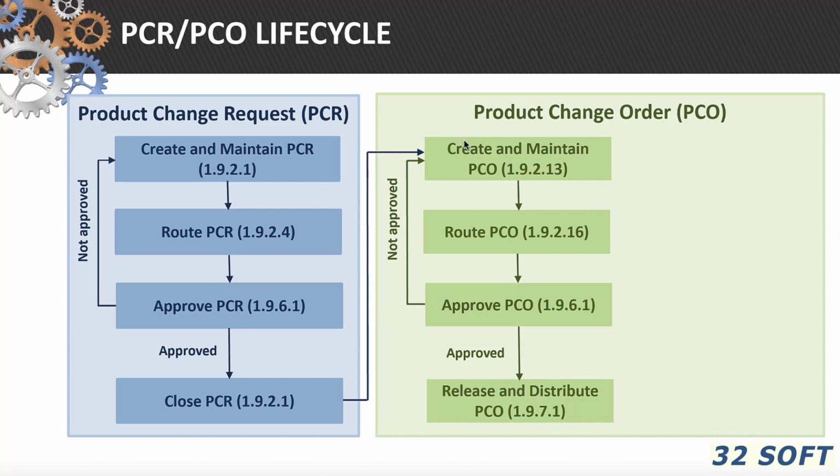The change date can be set as mandatory, or the manufacturer can be allowed to select a changeover date based on the least cost, minimum disruption, or other relevant factors. To plan for the effective dates for changes, the QED Incorporation Planning Report can be used to check for inventory levels and their monetary values of items affected by a change order. Effective dates can then be assigned using the incorporation selection function.